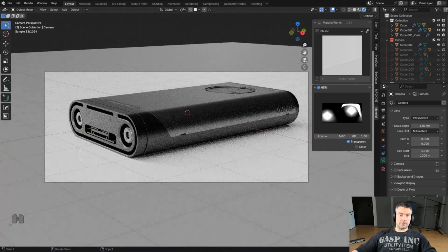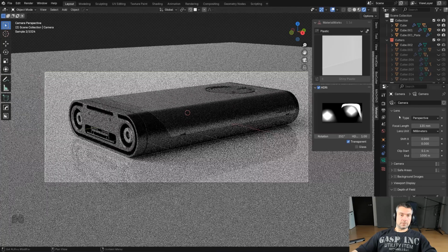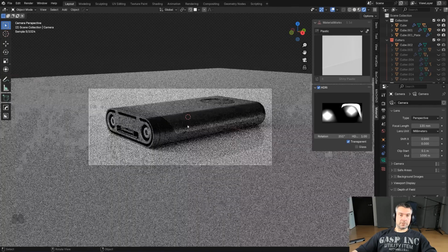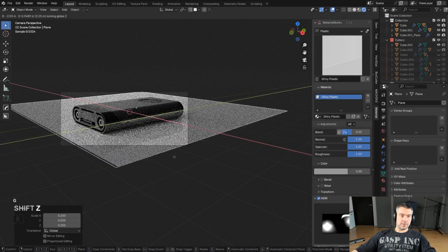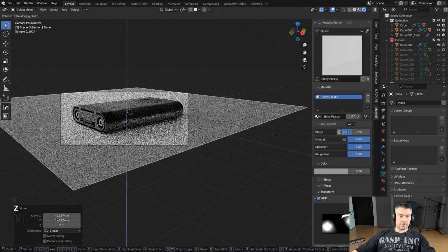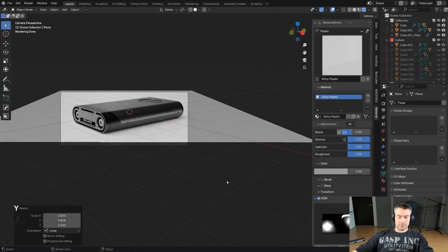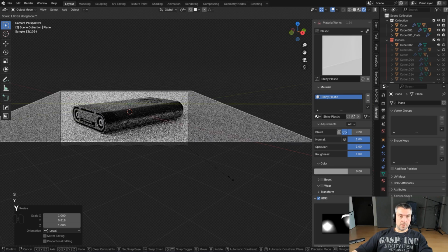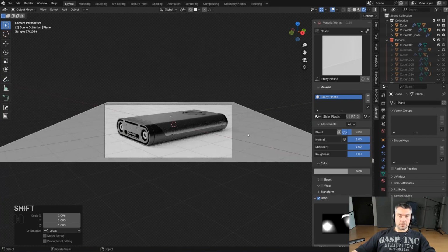The main feature here is the front. So we want to light it from the front. So the lighting comes from over there now and front, right? So this is good, but we could definitely scale this plane here. It's too big. G, Shift, Z, and move it in here. You don't want your plane to be too big, because it's gonna be obstructing the light. We can even rotate it to fit this framing, and maybe S, Y, Y, X, X. Scale it a bit here. There we go.